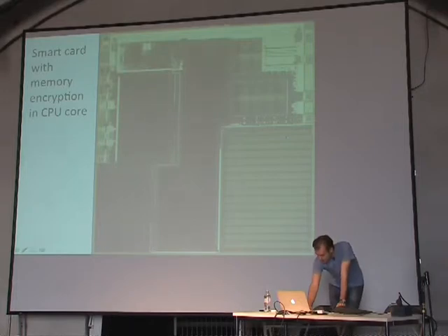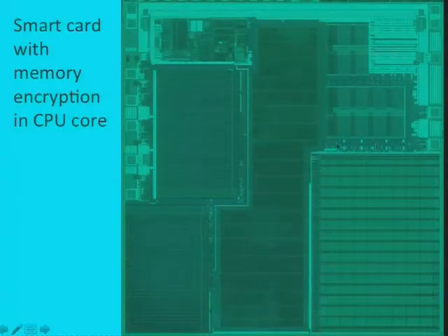Again, this will probably be a big area of, I don't know, it could go either way. So there's ROM and flash here. And there, of course, is a memory encryption function, but this memory encryption function and the CPU core and the AES function, this also is an RSA accelerator, and all of this is piled up in this big blob of random logic in the middle.